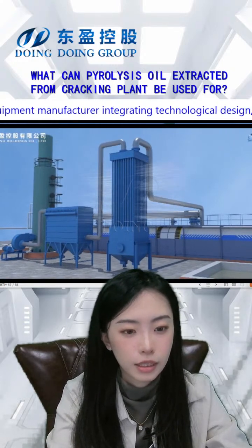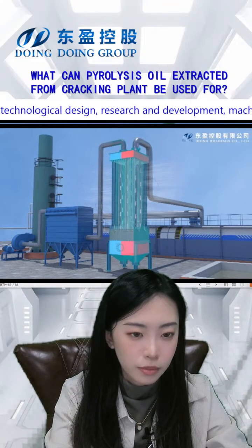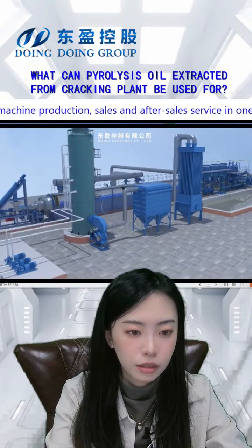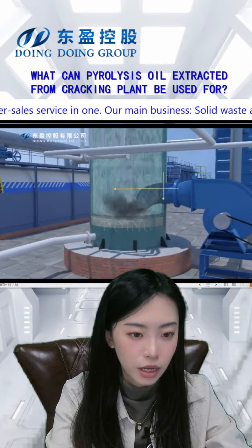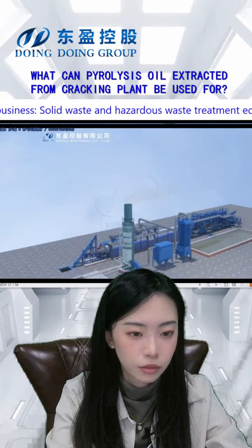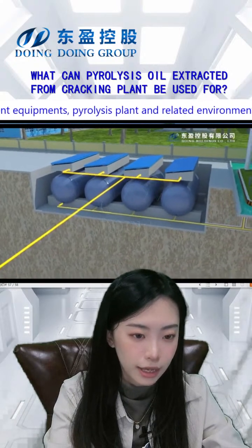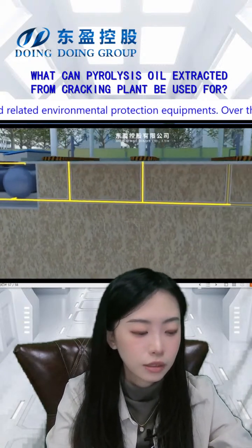This is a purification system, the last device that the gas will come to. This is a device to lower the temperature. In the middle of it is the post-dust collector. The last is the desulfurization tower, which purifies it. And this is the whole line. And the last step, we can pump the oil into the larger tank, to sell it or refine it. This is the whole line of the fully continuous pyrolysis plant.